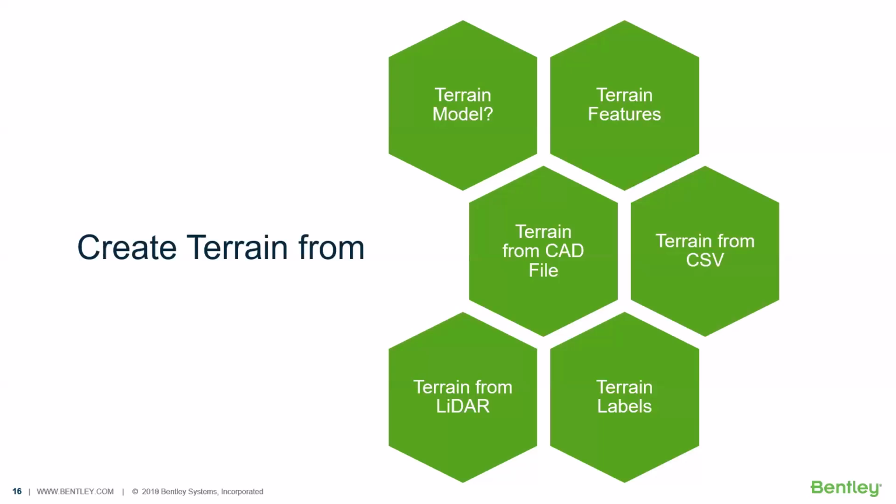Apart from that, something that's coming up very extensively is the LiDAR data, which contains millions of points in a particular survey, and it is very rich, highly populated data. So if we are using a product like OpenRoads, and if you have a LiDAR data file of, let's say, 700 MB, you're able to use that file to create a terrain within minutes. So you don't have to wait for a longer time. You use it and you get it pretty easily.